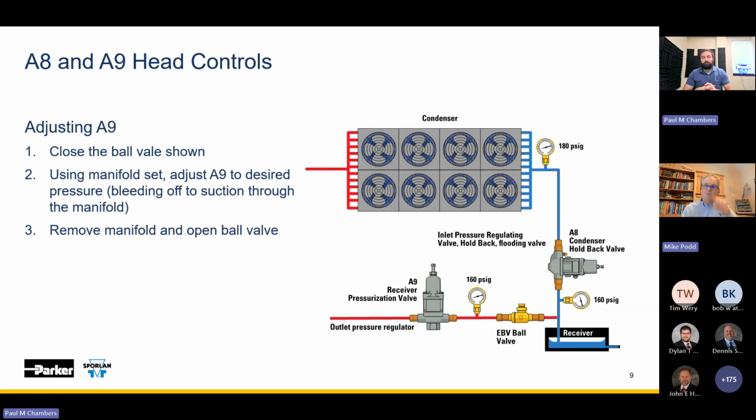Then, drop at 220. One turn is 70 psi. So one turn of rotation, I can set that for 150. So that would be approximately where it would be. Instead of one turn, I would adjust accordingly to get it to have a 180 holdback capability there. Then it would return to wide open.